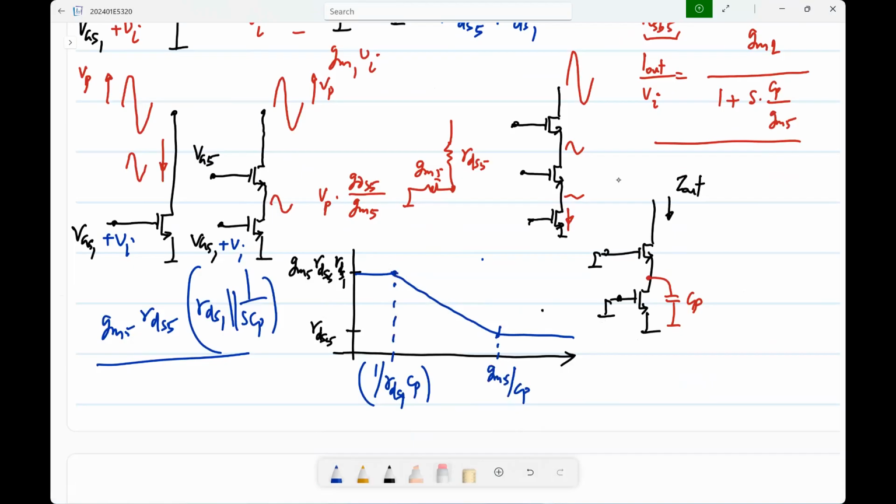So this kind of thing is also important because, like I said, you want to get insights into the problem. So in this case and in general, what was the fundamental mechanism behind getting a higher output resistance? It is negative feedback, right?